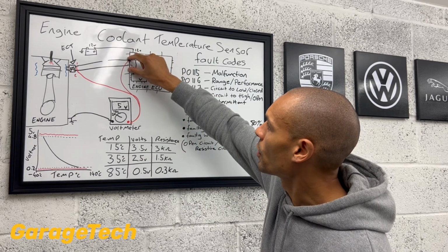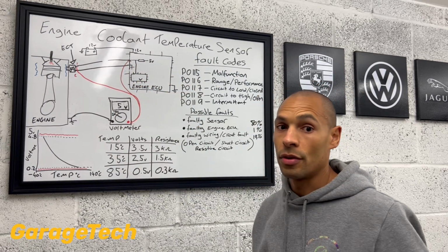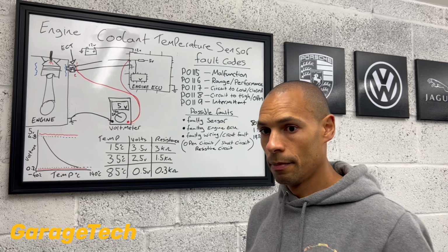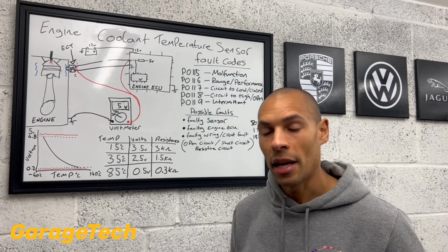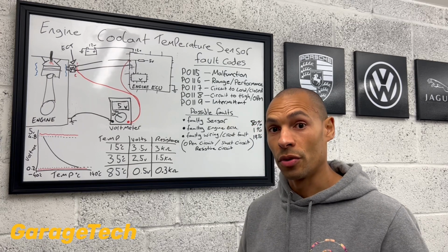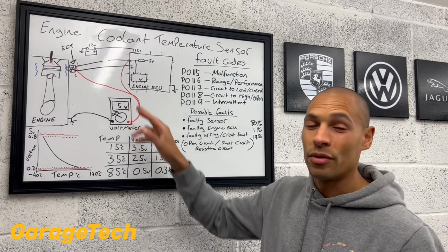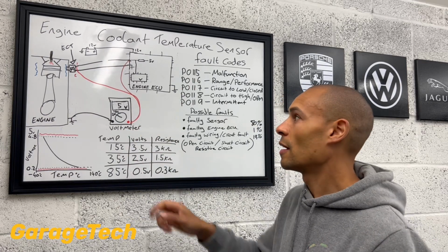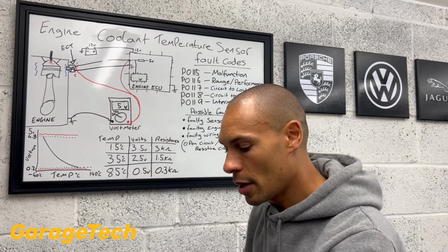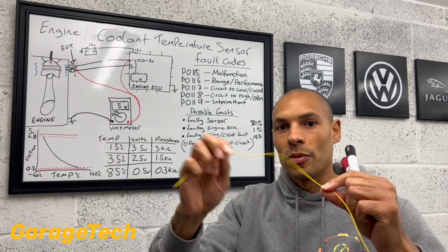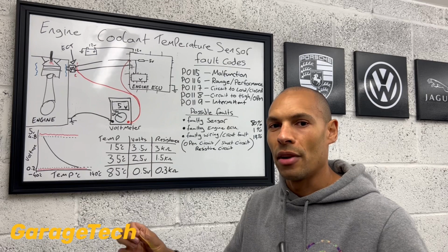So you could unplug the plug there, unplug the plug there, and do a resistance check on that wire, often known as more of a continuity check. But personally, I don't like to do the continuity checks, and you might have multimeters that beep for you, but actually I'd rather do a resistance check, because if that piece of wire only had one strand left in it, and it was only when you're wiggling the wire around that it becomes open, potentially with doing the continuity check, you may not find that.